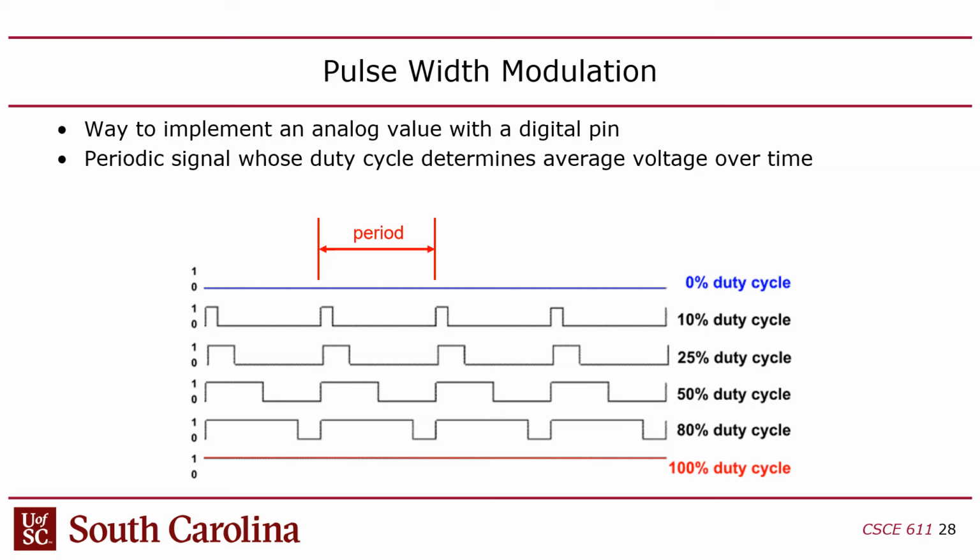If you're using a PWM signal to brighten or dim an LED light, for instance, and you choose a frequency that's too low, you'll see flickering. You'll see the light flickering, and it looks kind of bad, right? So if you don't want that weird flickering effect, you just crank up your frequency on your PWM, and you get a nice dimming effect on your LEDs, right? And this is how, of course, LEDs are dimmed, generally speaking. Again, it's a PWM signal. So everything from lights inside a car to your charging light on your MacBook, they're all PWM control.